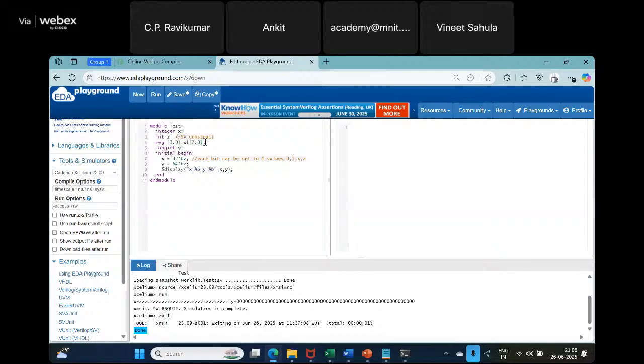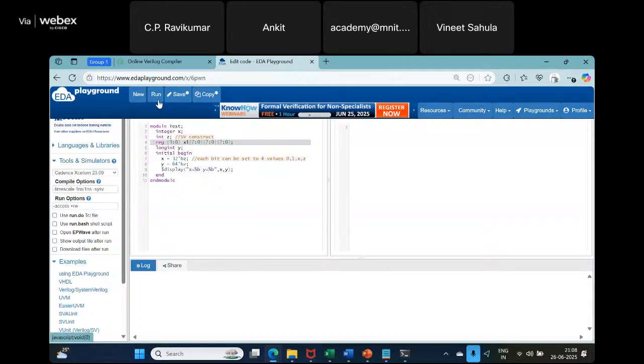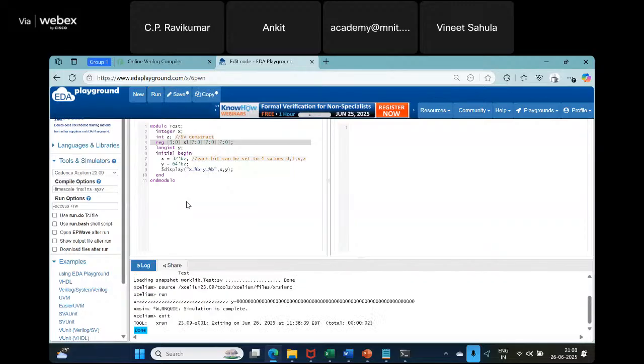But what SystemVerilog is able to do is multi-dimensional arrays. SystemVerilog can handle any number of dimensions. In this case, I have shown 3Ds. That means you can have 3 indices. In fact, you can have a fourth index. So this is allowed in SystemVerilog.